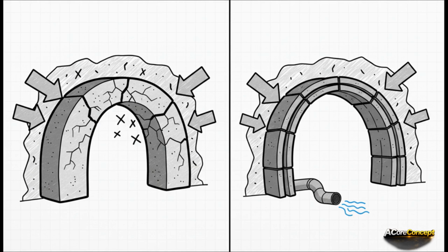in the Himalayas. In squeezing ground, if you build a perfectly rigid support, the mountain will simply crush it. Your supports must be designed to yield and safely accommodate plastic deformation. And, as we've seen, water has to be aggressively routed before it becomes a hydrohammer against your tunnel face. Flexibility and proactive ground treatment are quite literally your survival tools.